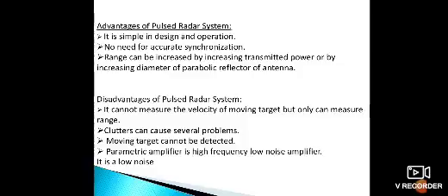Whenever we use a radar in those conditions, the echo signals returned from the ground, sea, rain, animals, insects, or any atmospheric effects cause serious performance issues in our radar systems. That is called clutter.